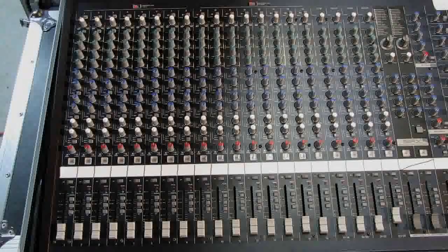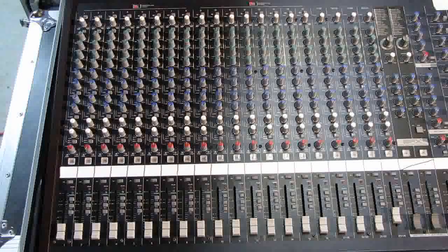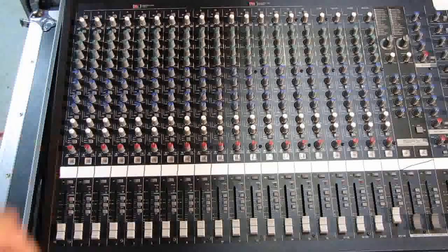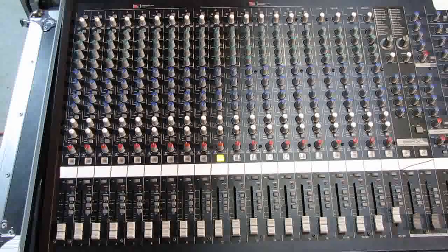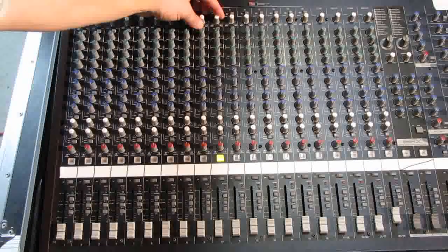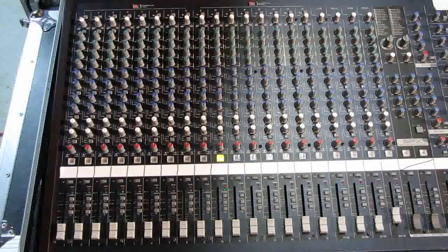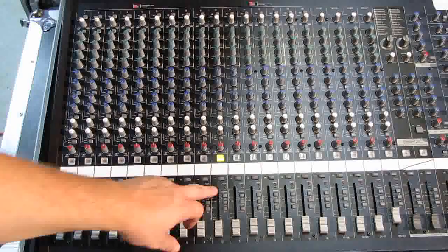Okay, so to start, we're going to use the Sennheiser E835 microphone on channel 10. So the first thing we want to do for our signal path, and as you remember, we've got the cable coming in the back into channel 10, is turn channel 10 on. Right now I'm talking to the microphone, but we don't see any lights. So the first thing we've got to do is set our gain up some just to make sure we have some signal coming through. Check 1 2 1 2. Okay, now as you can see right there, we've got the signal coming through.